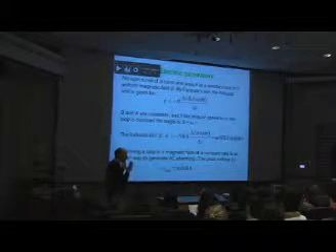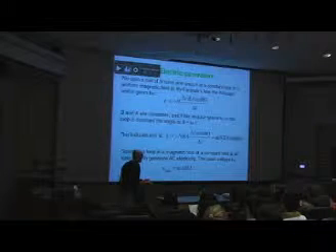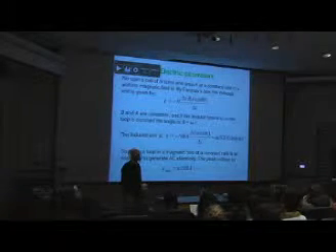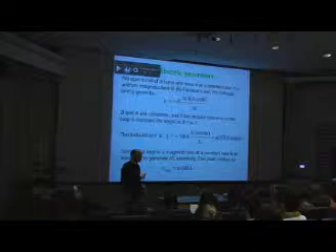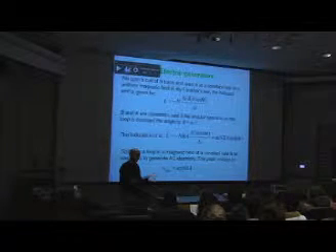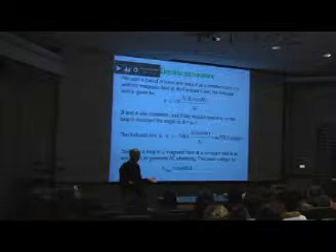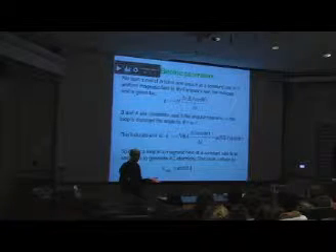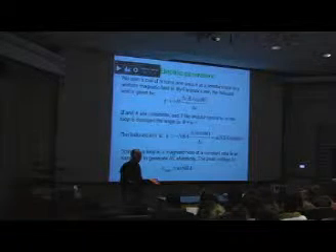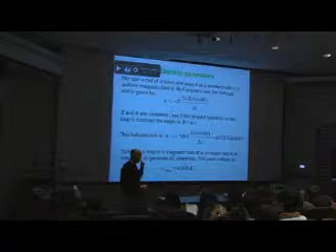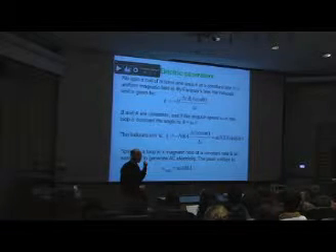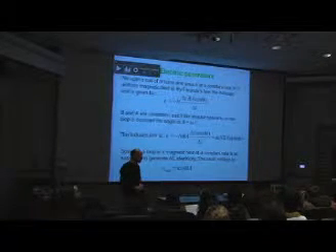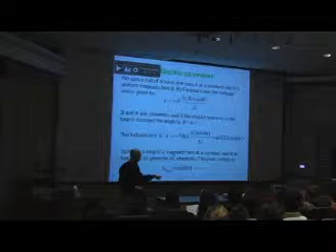Okay? You just got to get permanent magnets that generate a nice strong field way bigger than the Earth's magnetic field, and then you can have, in fact, you have to rotate, if you're in North America, at 60 hertz. Okay, 60 times a second. You can't go 2 million times per minute. You actually have to go 60 times per second because that's the frequency you need to come out of your wall socket.